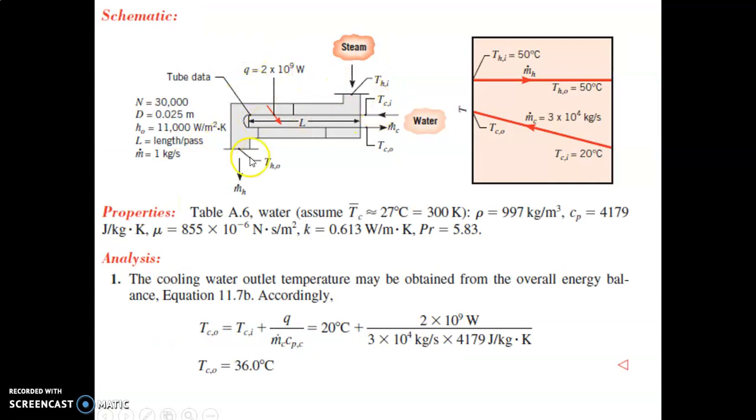First, it is better to draw for yourself how the design of the question looks. We have a shell and we have a tube, inner and outer, passing through the shell. This diagram will help us understand how the flow is going on. From the data they provide, we will find Cp from the inlet temperature only. Don't assume, please, in the exam. From the inlet temperature we will find Cp to be able to calculate the rest of the data. The heat, the inlet temperature and the mass flow are provided, so we can get Cp from the table.